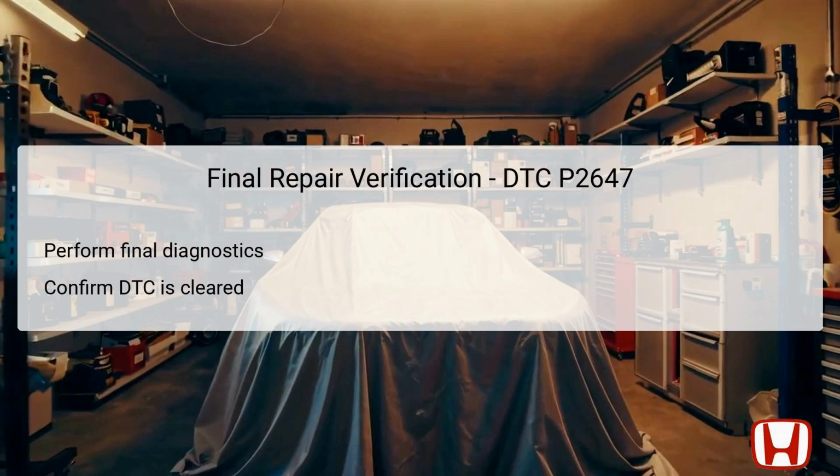This involves performing final diagnostics, essentially running through the initial steps of checking the engine oil level, conducting the VTEC test, and ensuring oil pressure is at the specified level. Confirming that any diagnostic trouble codes, DTCs, have been cleared is equally important, indicating that the repair work has resolved the underlying problems. Additionally, the technician should verify that there are no lingering electrical faults and that components, such as the EOP sensor and rocker arm oil control valve, are operating seamlessly.